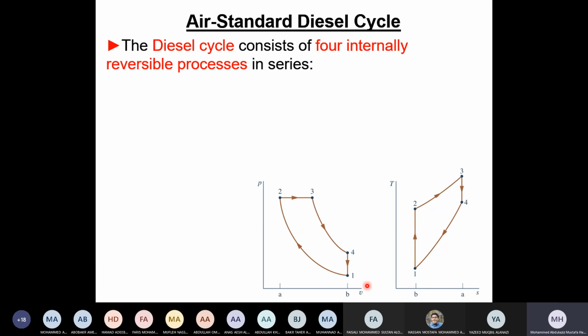So the difference from the Otto cycle, where this is vertical, is that in this cycle the heat addition is horizontal like this. Why do we make it horizontal? It is just to fit the actual process of the diesel engine. First, from 1 to 2 is isentropic, as in the Otto cycle, so 1 and 2 are the same as the Otto cycle. The difference is that R will not be 9. R will be around 16, 17, or 18, because this is a diesel engine.